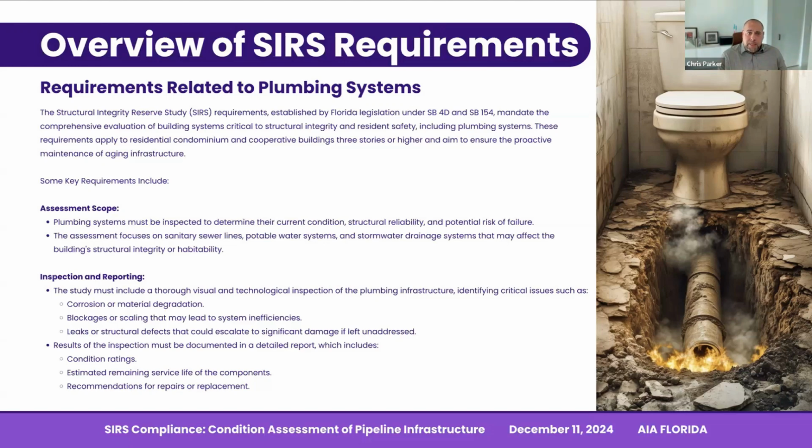And it's important to notate too, that you could be in a building where the south side of the building has noticeably more degradation than the north side. So it's important that when an assessment is done, it is truly done at a 100% level of that building, going into every sanitary sewer stack, every potential piece of pipe that is accessible.